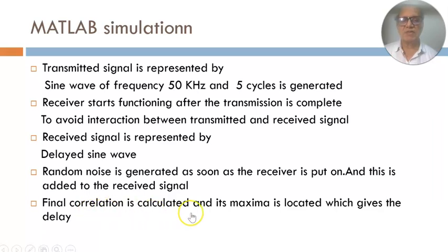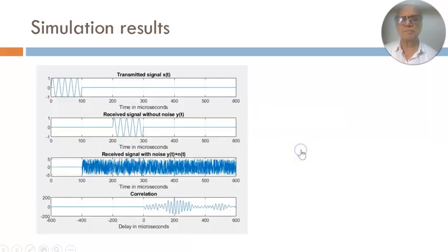We'll explain this further, but for the time being, just note that we generate a signal which is the addition of the reflected signal plus the noise, and then find the correlation of the transmitted signal with this, delaying the transmitted signal as we find the correlation. The point of maximum correlation will tell us what the delay is. This will be better understood as we go on.